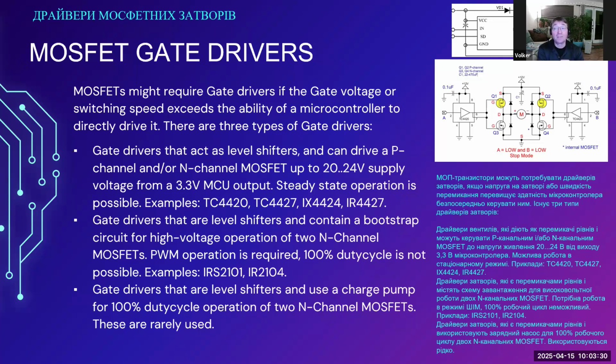Otherwise, if you try using it in a steady state application, the gate charge of the high side MOSFET would slowly bleed off, and it would not turn on anymore. So even for a standalone high side driver, you need this type of driver circuit that uses a bootstrap capacitor. It needs to keep switching.